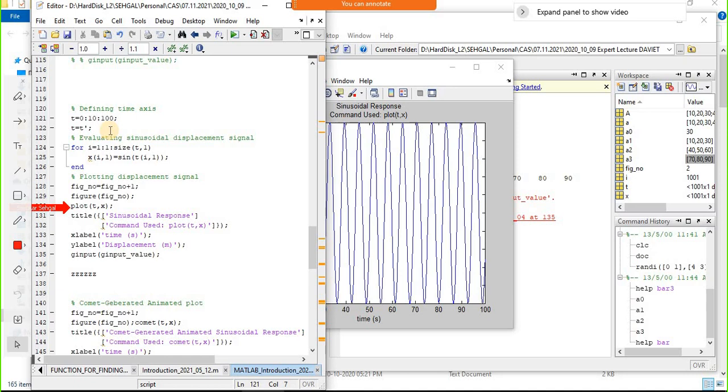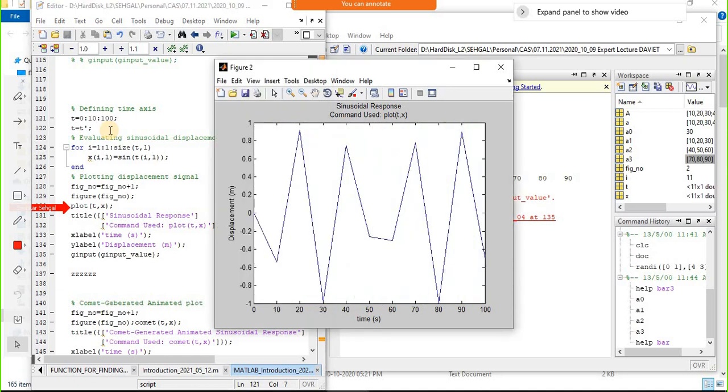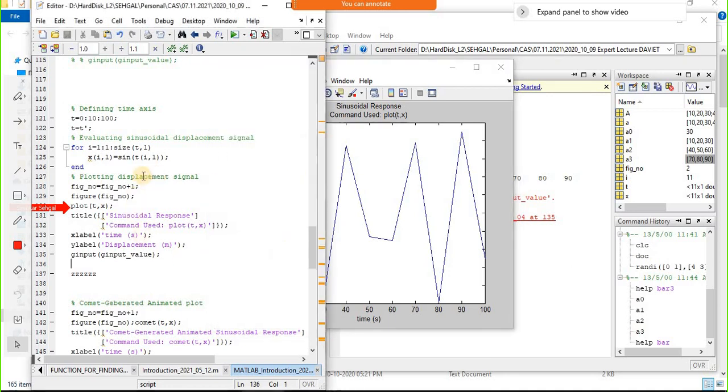If you do not set your sensor sampling frequency properly, this kind of problem will be there in the signal processing. When you experimentally measure the signal also, such kind of problems may arise if the sampling frequency is not good enough. So there is some specific criteria, the Nyquist criteria, based upon which the sampling frequency is selected. It depends upon what kind of frequency you are going to measure. So here let us first go into this.